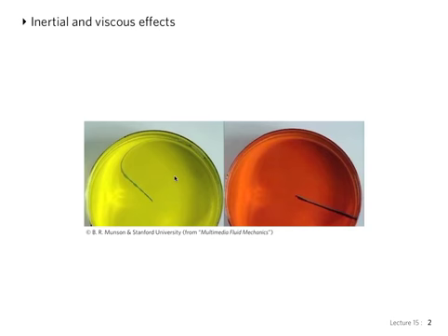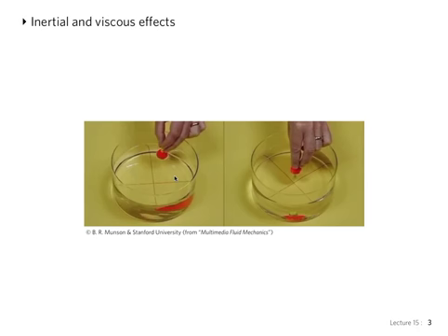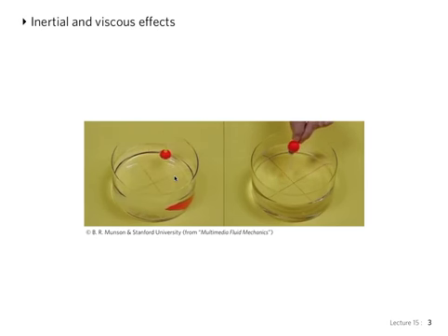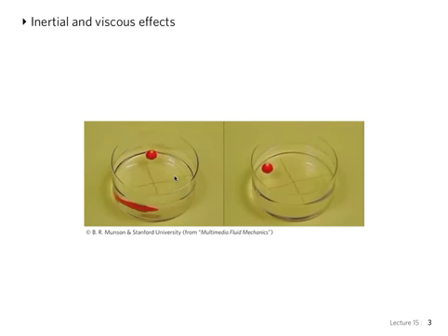And here is another example that we have, two videos. So now, again, they will start rotating. You see the one on the right is very viscous. The one on the left is not very viscous. They start rotating the container, and this little floating cherry or something doesn't really move very much. The one on the right, the whole thing moves together because it's dragged on by viscosity. And so on the left, the inertial effects are dominating. On the right, the viscous effects are dominating.